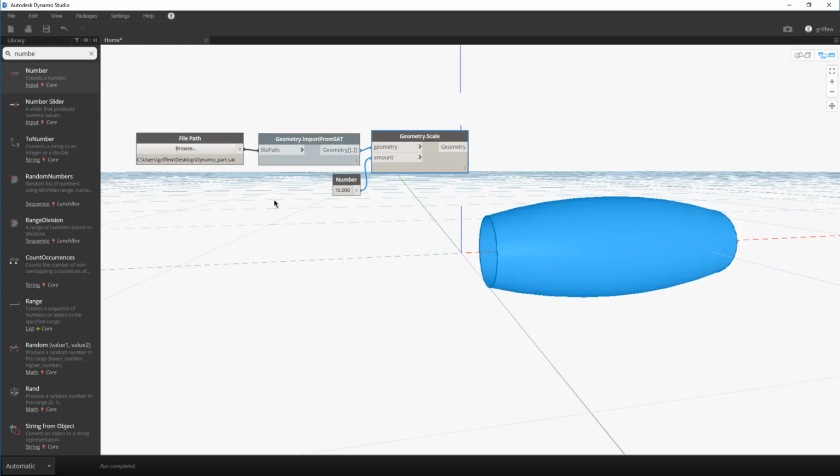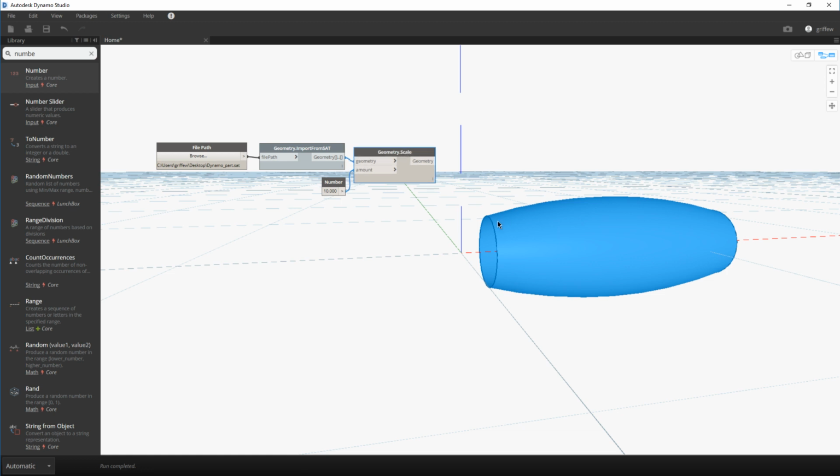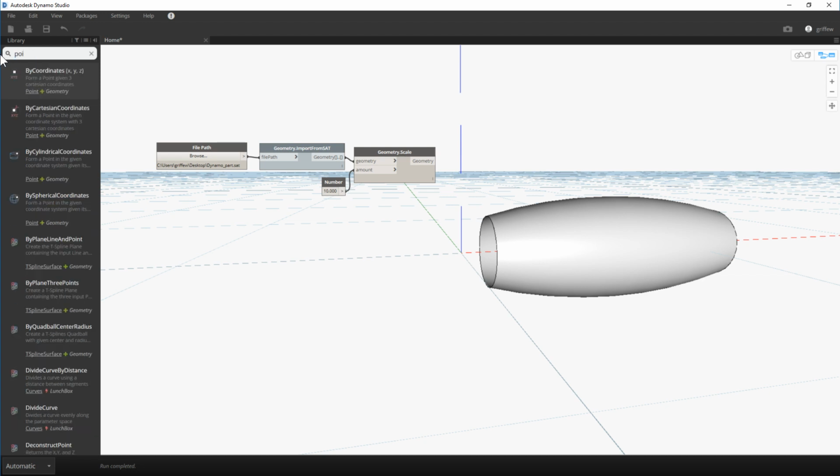So the next thing I want to do is actually start to add some points along that surface, where I want those little nodes, those little balls, the bumps to go along this surface, right? And I kind of want to grid it out. There's one quick parameter that you can add. It's a surface point at parameter, right? So there is a list online. If you do a search for Dynamo commands or Dynamo library, you'll find a list of these different commands that you're trying to do.